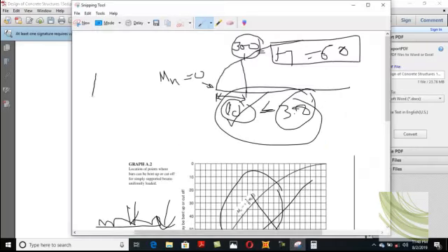You must know about the cross section of the beam, that is 12 inches, and there are 4 bars. This bar and this bar are number 9, and this bar and this bar are number 8. So how can you get this clear spacing? You must know this calculation, and I did this calculation so many times in development length.